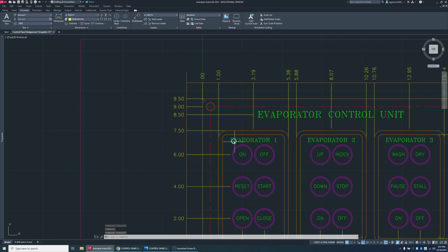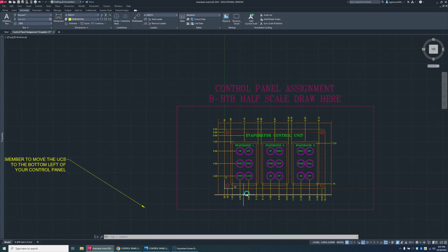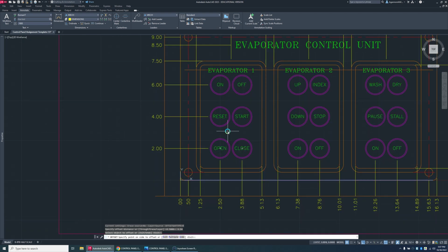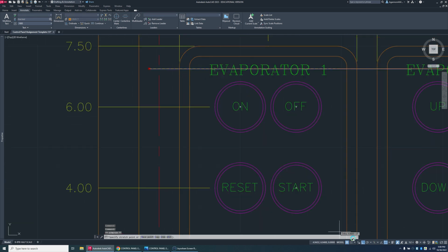And then I want to do the same thing here. Let's just make sure our line is only coming over to right about the edge right here. So I'm going to offset that by 6.94 from the bottom. So 6.94, and this bottom layer here, go up. And then I'm just going to bring this over to right where I want to go to. I got that on, so that's good.